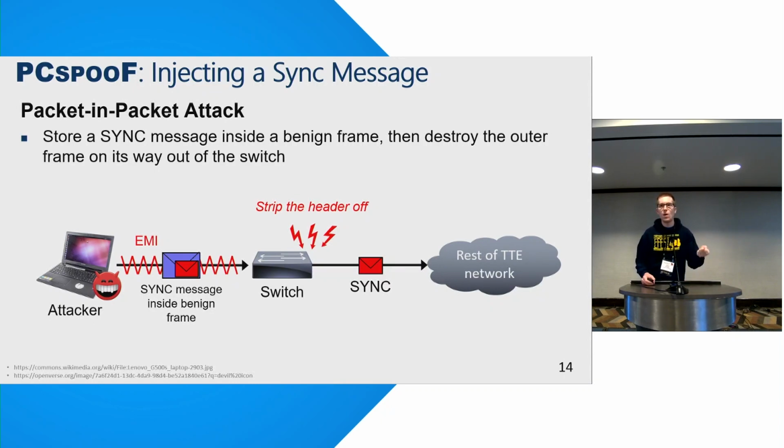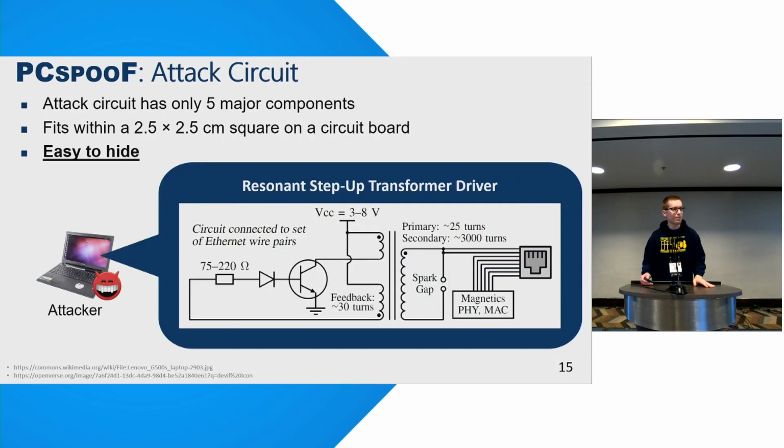And the reason we want that is because when the link goes down and comes back up, that act of the link recovering can actually cut the message in half in flight and just result in the tail end of the payload going out on the wire. So if the CRCs are the same, then the resulting fragment that ends up on the wire we can make look just like a synchronization message, and then downstream devices just can't tell the difference.